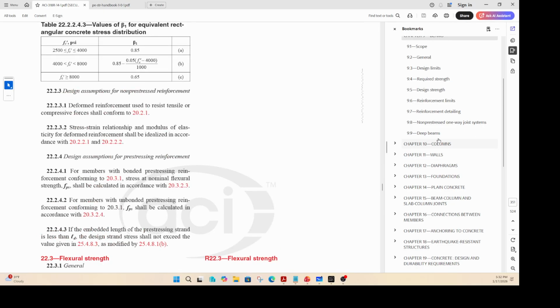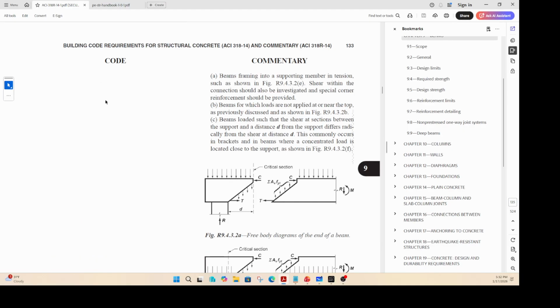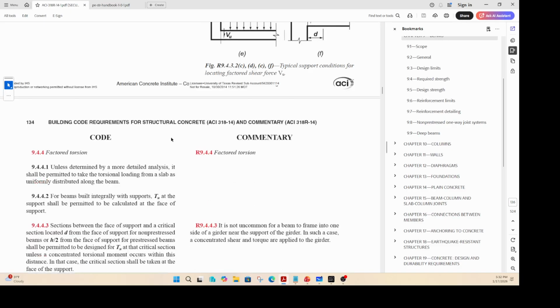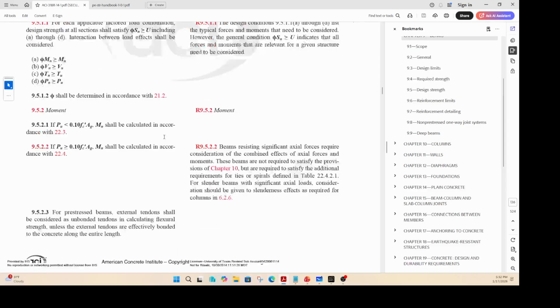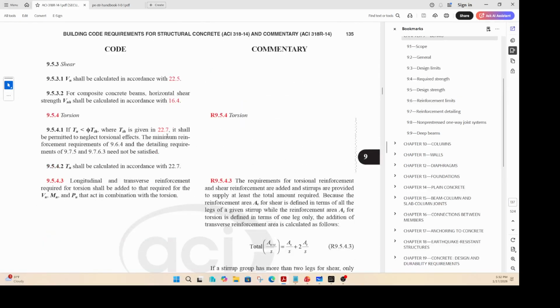Then we will go back to page number 135. Okay. At least we are in the beam section here. So that's how you calculate your nominal moment. Now we are talking about nominal shear, Vn. How do you calculate your shear capacity of a certain beam given a certain amount of reinforcement? Okay. So shear is not taken by the longitudinal reinforcement; that is neglected.